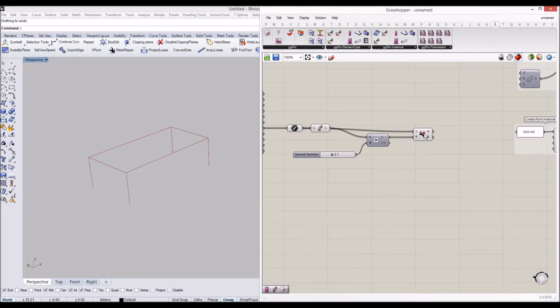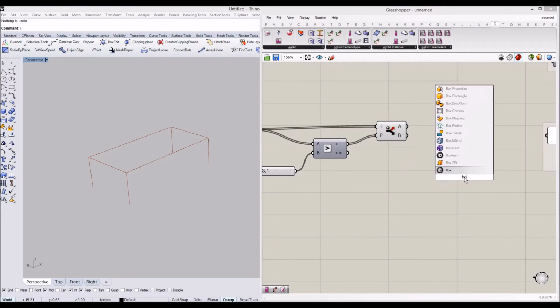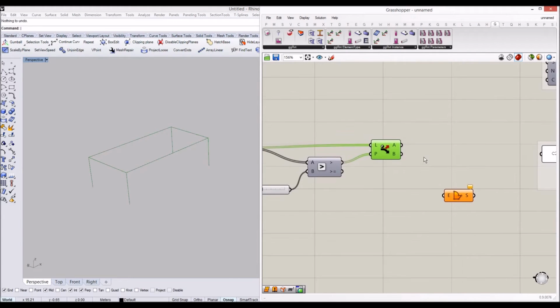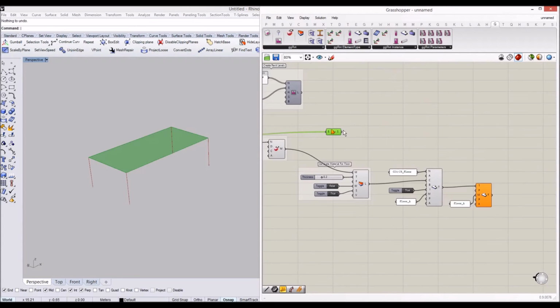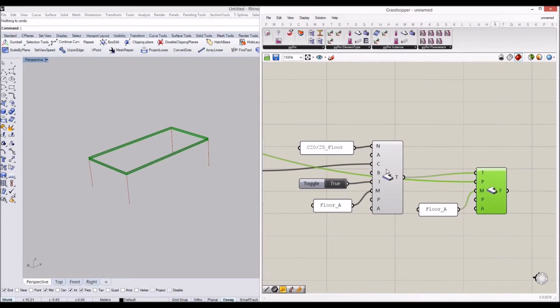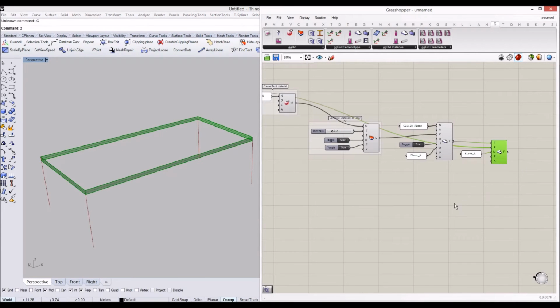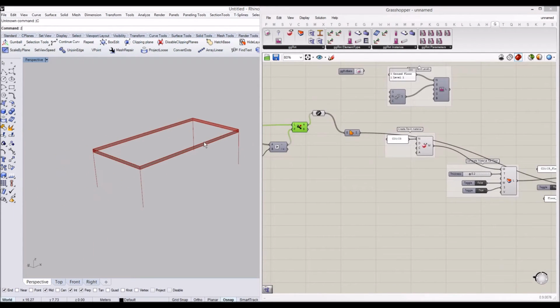So what you can do in here, we have those lines that we separated from our geometry, and now I'm going to use boundary surface, for example, and let's see which line is which, we'll find out. So this line is the one I want to make a boundary surface. Okay, so I'll use this surface model to create the Revit floor. So we provide this boundary surface to create the Revit floor. So the floor is created. Now we'll create the columns and beams in GeometryGym.